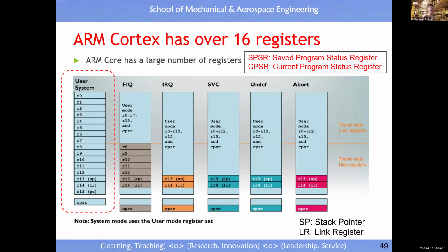SP means stack pointer. This also is a new concept to you. This is something useful when you do multitasking. That means we suspend one application. Okay, then the context of the working memory must be stored into a memory, a temporary storage memory. Then what is the first address of this storage memory? This address is stored inside R13. Okay, it is this operation.